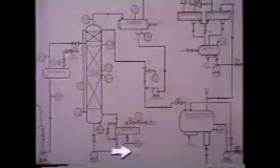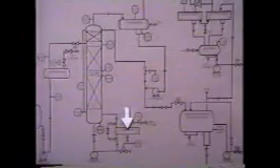For example, the operator may receive a telephone call telling him to step up production. It'll be up to him to make sure that adjustments are made to produce a larger volume of product. These adjustments involve gradually increasing the feed rate of mixture going into the column, increasing the top and bottom takeoff rates, and increasing heat to the reboiler. In addition, he may also increase the reflux rate.